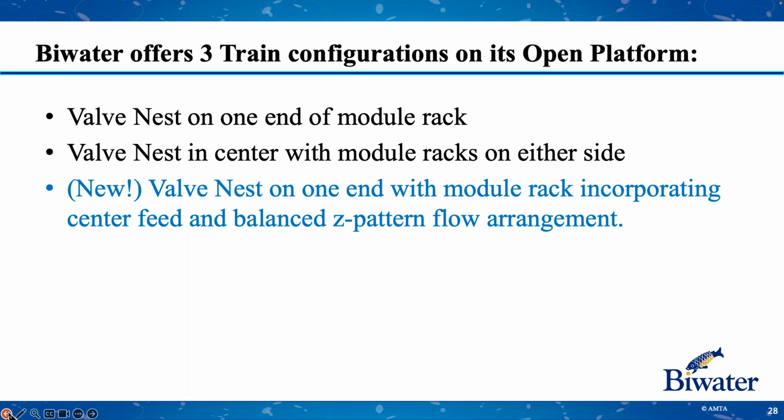So what's important and what we've learned, there's a few manufacturers that have the proprietary systems. They have what some call a butterfly design, where you have a center feed, kind of a valve nest in the middle of the unit, and then there are modules and racks on either side. The good part about that is that it allows for quicker draining, quicker fill times, and more balanced flow between all the modules.